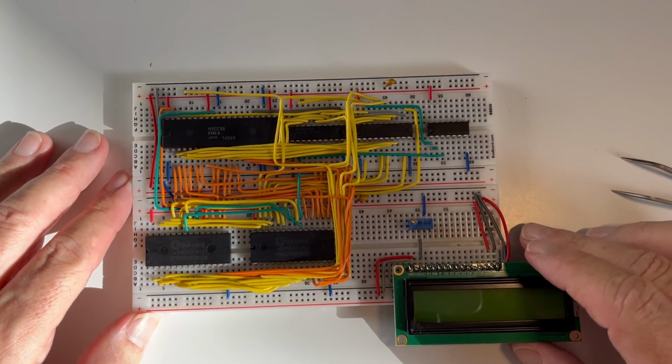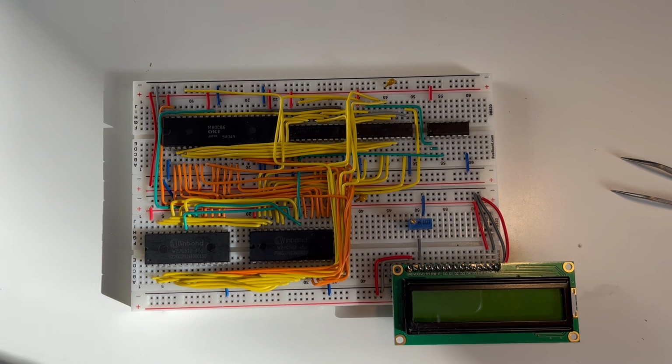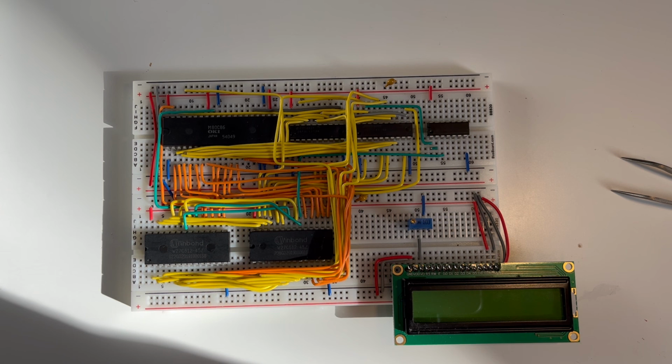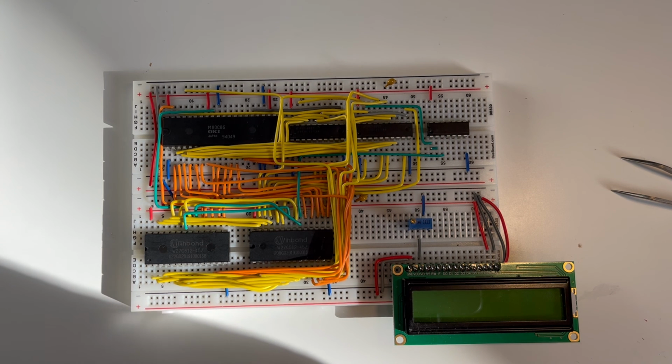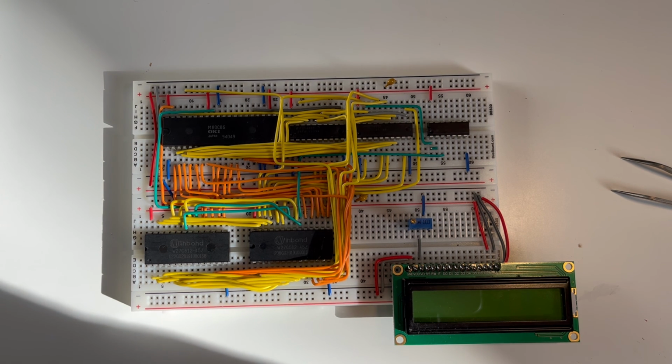What we're looking for is an enable pin, much like the enable pin on the EPROMs, in exactly the same fashion as we did for the EPROM. We want to set the address for this LCD device. The EPROM we set to be in the range 8000 to FFFF, and so when the 8086 is talking across the bus, the only device that responds is the EPROM.